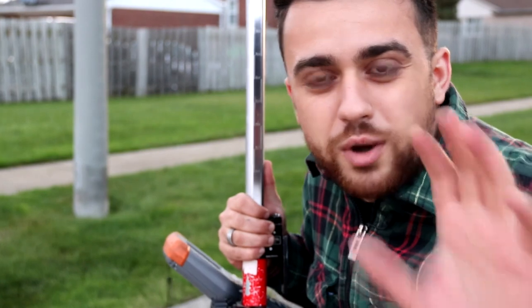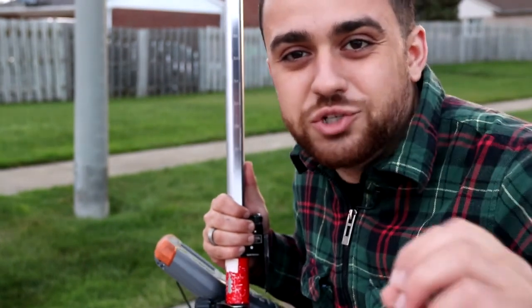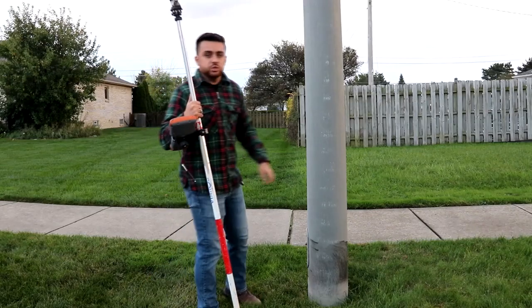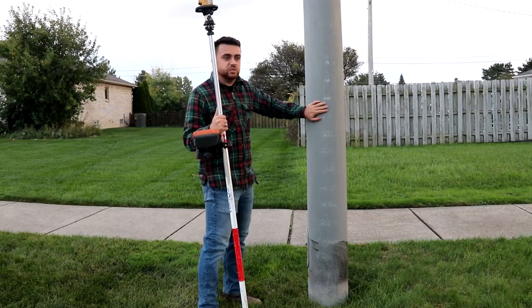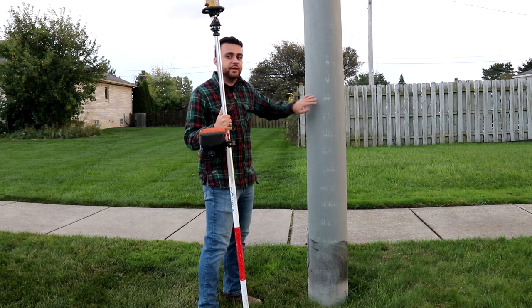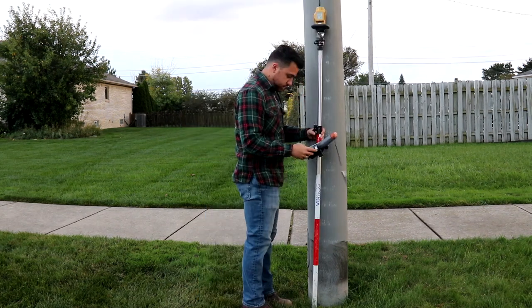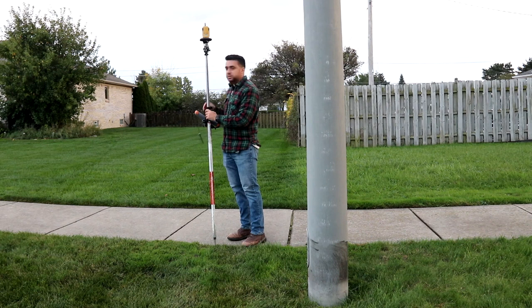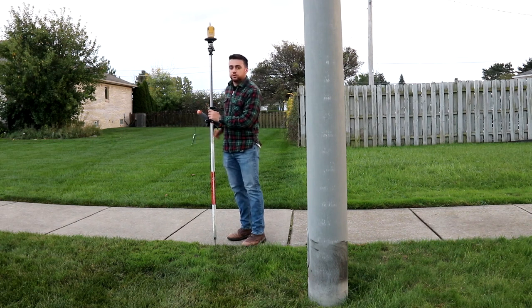Now you'll notice we're going to run into our first major feature, and that is this gigantic light pole. What we're going to do here is just get as close as we can to the light pole, and we're going to take a shot and call it light pole. Light pole. This will be a new sidewalk, so I'm going to call it concrete 3.